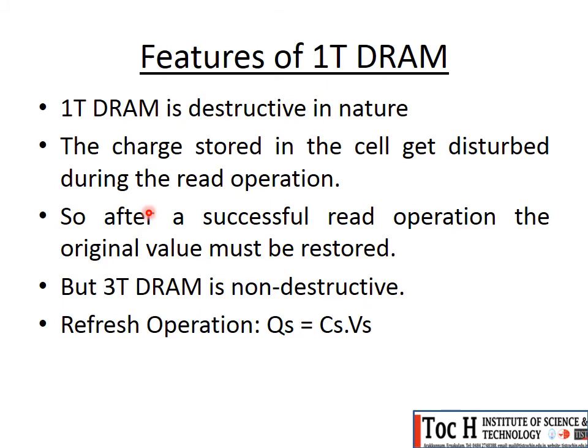So after a successful read operation, the original value must be restored. If a logic 0 is present in the capacitor, what happens? Some voltage will be added to the capacitor. So actually the capacitor voltage is varied during the read operation. So after a successful read operation, the original value must be restored.